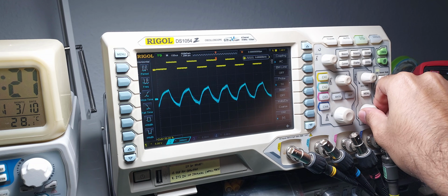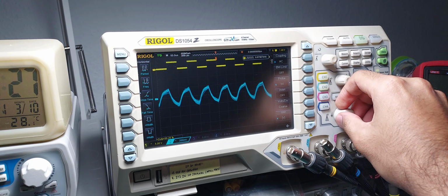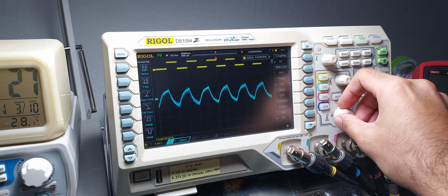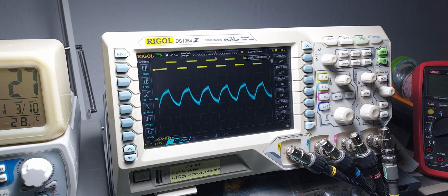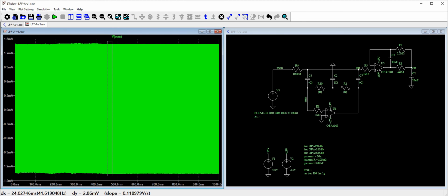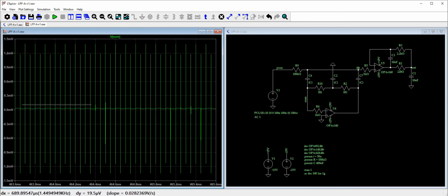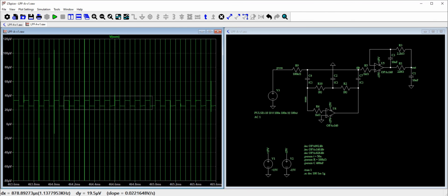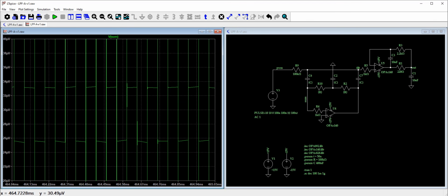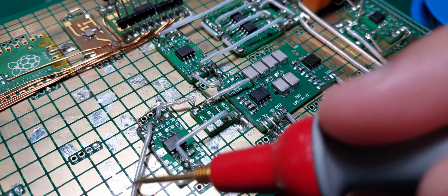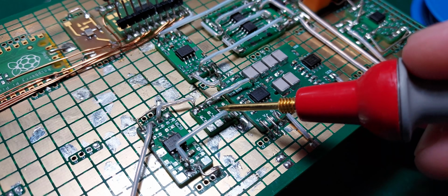Although 40 microvolts peak to peak was a huge improvement over the discrete attempt, for a DAC that was 1 microvolt settable, it was still undesirably large. Apart from the op-amp's limited bandwidth, another factor contributing to filter ripple is finite open loop gain, where the op-amp can't fully drive the summing junction to 0 volts, resulting in a square wave at that node. Taking a page from the multi-slope book, I decided to experiment with a composite configuration.